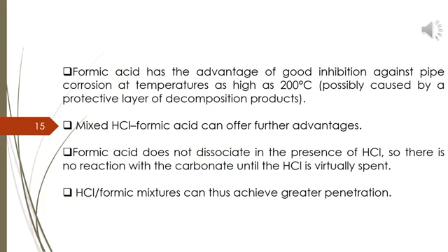Since formic acid will not be decomposed, the mixture of HCl and formic acid will give a greater penetration into the well, and that will help to dissolve the salts which I have mentioned, so that the transport of oil and gas will not be tough, if the sediments do not have these hard materials in the way.